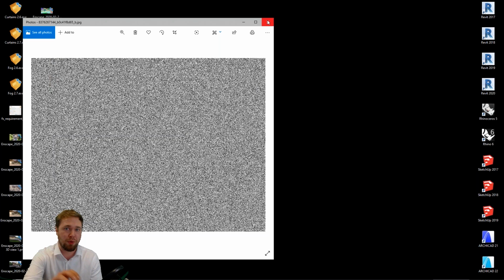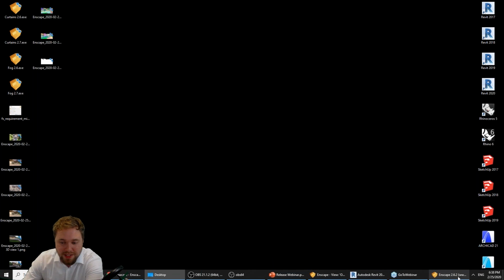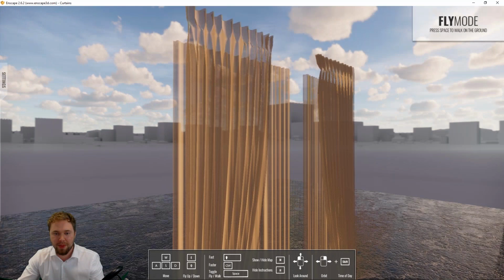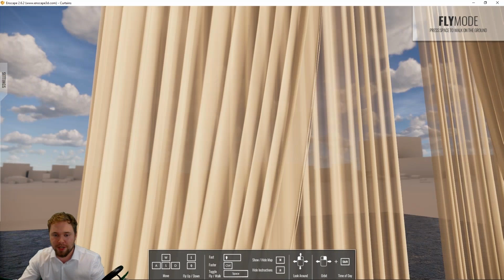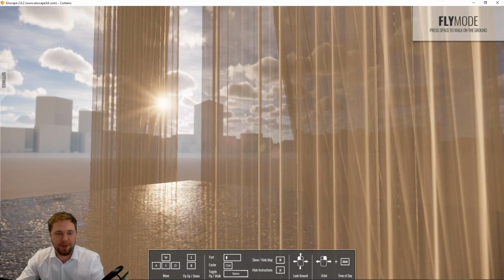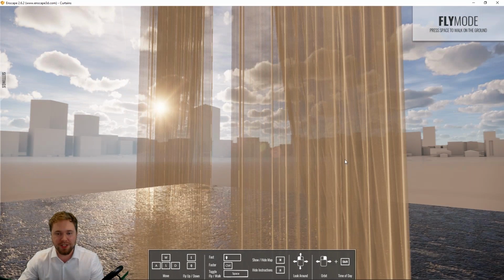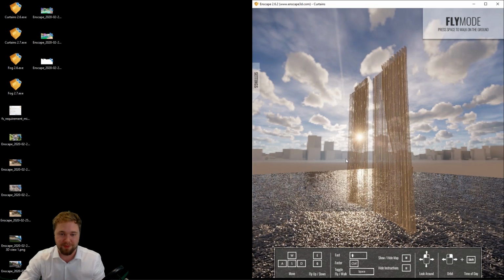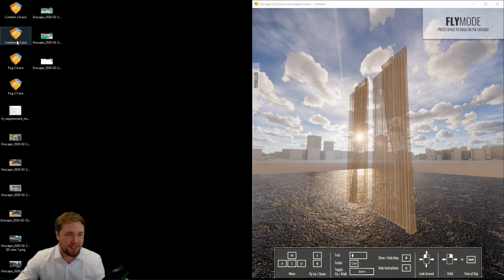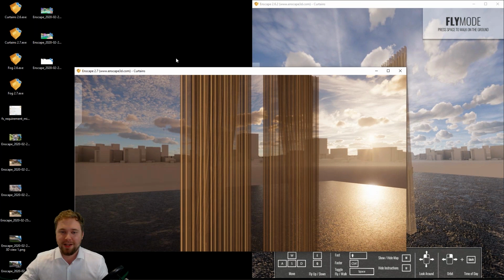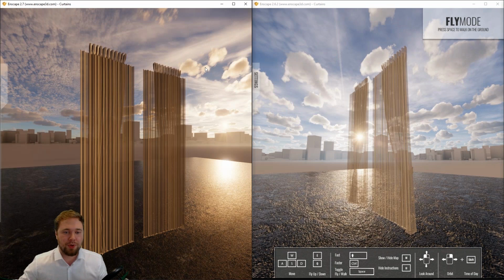What you want to do is apply this to a surface as a transparency texture. And this is what it looked like before. So you can get nice results with it. But you see, as soon as we have two layers on top of each other, is where it does not really look that realistic anymore. And this is also something that has changed with Enscape 2.7. This is what this experiment would look like now.